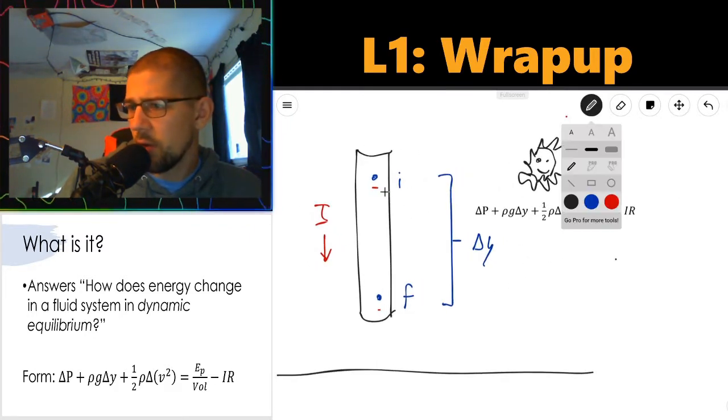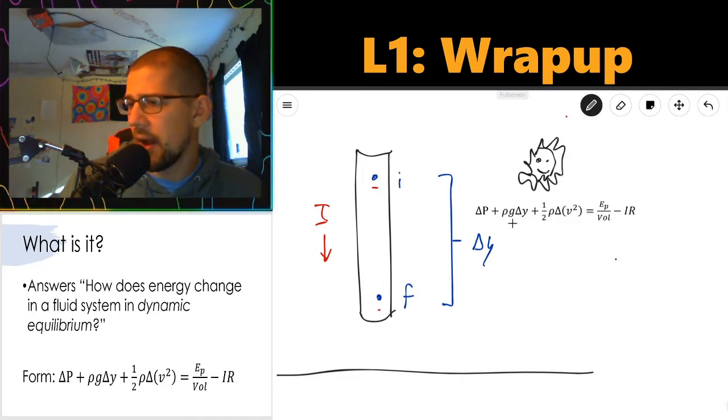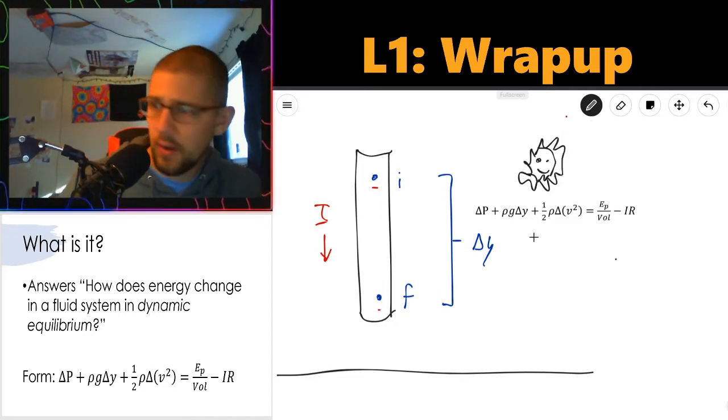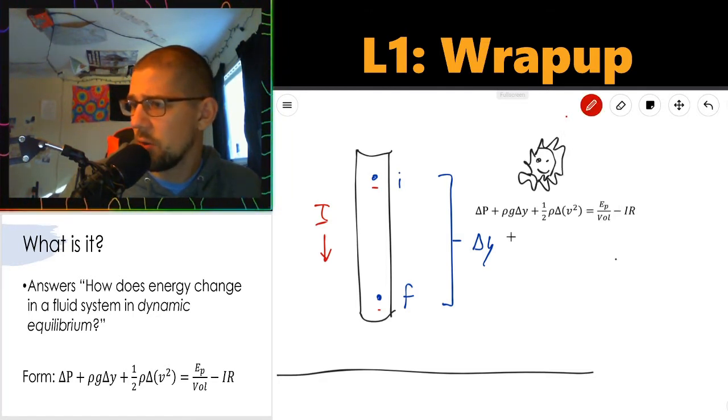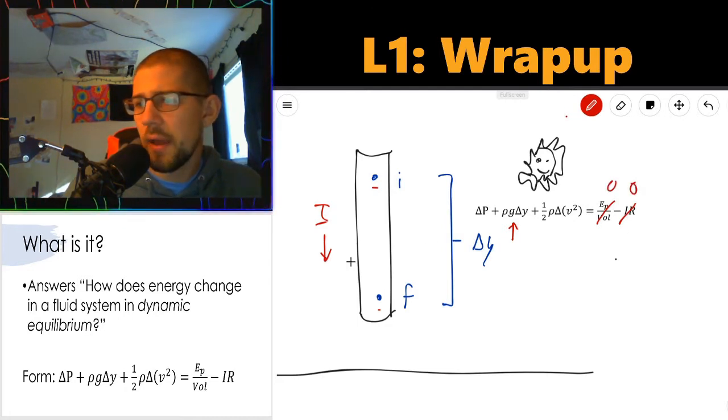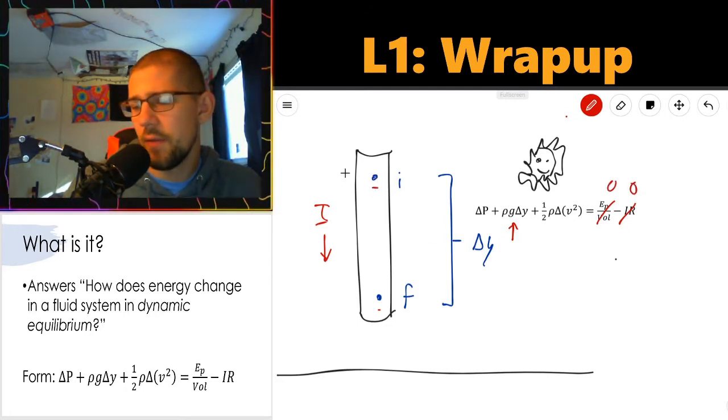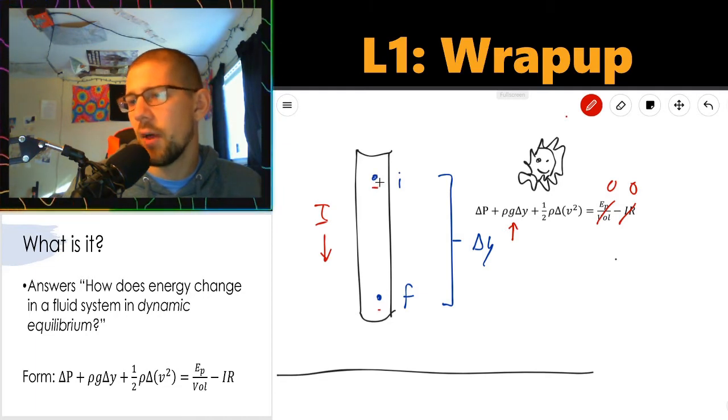Well, I've got current that's flowing down this pipe. The pipe is oriented downward, so it's dropping in height. So we're going to have our gravity head term change. That one's changing. I've also got no pump and no resistance, so this side is 0. Now, my initial thought is, as with anything else you drop from one height to a lower height, I'd expect that the velocity at the lower side would be higher than the velocity at the upper side. Let's check that.